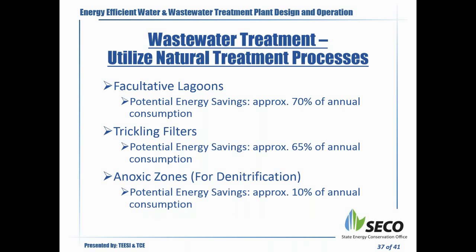And the type of wastewater treatment that utilizes natural treatment processes, of course, include these facultative lagoons that have a stabilization pond, which is a deeper pond, followed by oxidation ponds, typically 2 of them, that utilize the blue-green algae for oxygenating and removing your BOD.